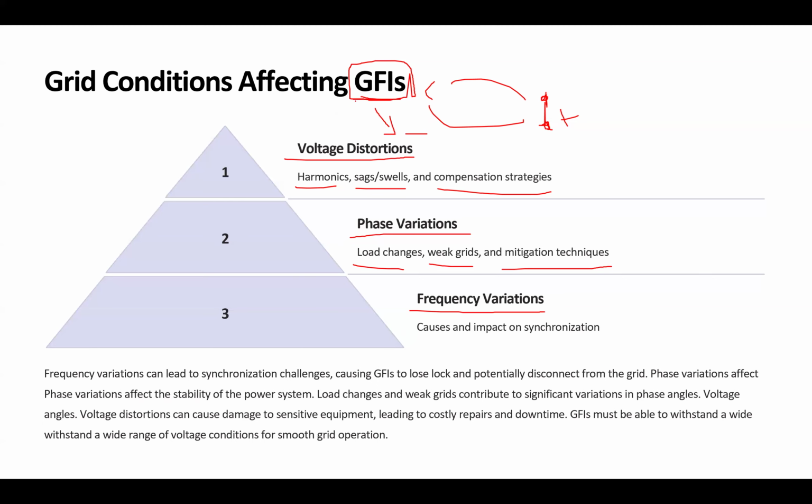If the PLL would not catch the frequency variation for any kind of reason, malfunctioning, or the variation is too low, and we kind of filter out the variation because we saw it as noise, anything that could happen. If the PLL cannot follow and cannot detect the variation, what happens is that the frequency variation would translate to the phase angle difference.